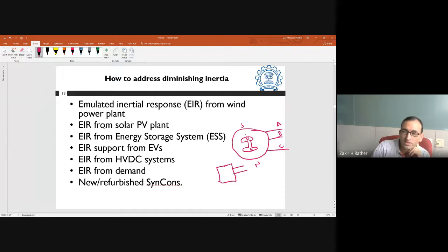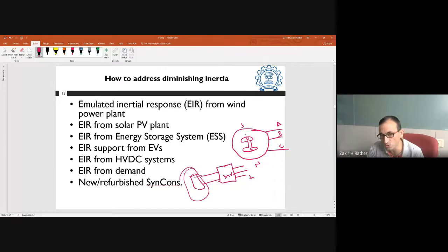So what you have is this inverter, and here a DC link, and here the source, whatever, wind or solar or battery. The frequency of the grid can fall here. The energy source on the DC side is not going to detect the frequency decrease unless it is indirectly told that there is a frequency decrease in the main grid. So it is a kind of blind about what is happening on the grid side. The energy source on the DC side of this inverter is entirely unaware of what is happening on the AC side of the grid.